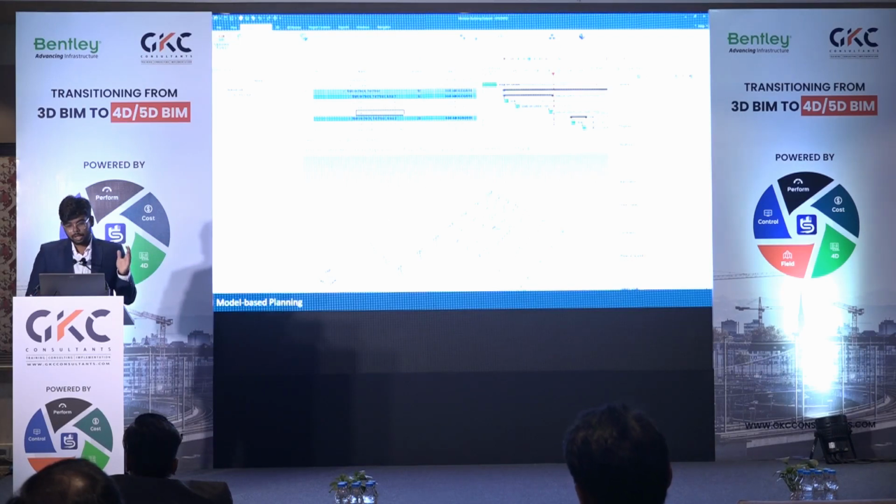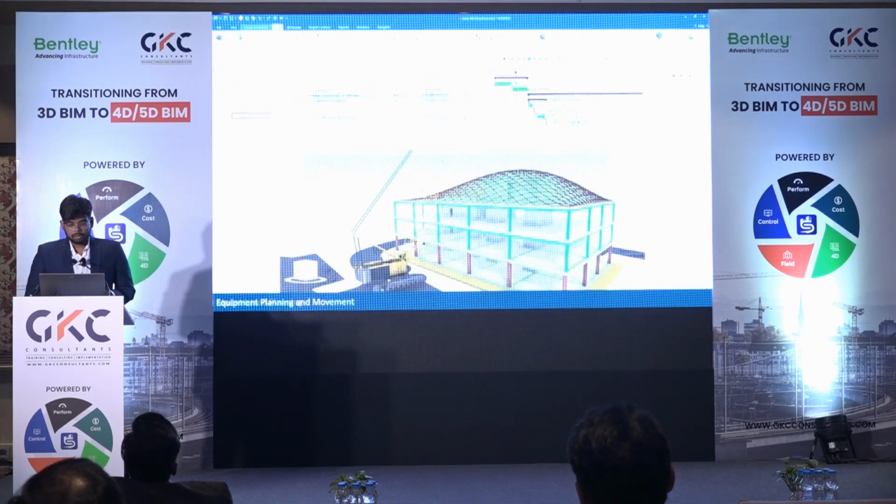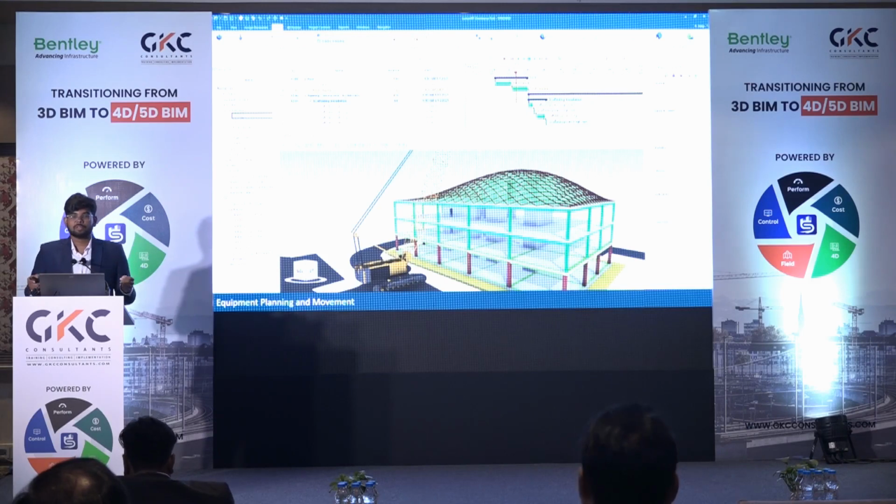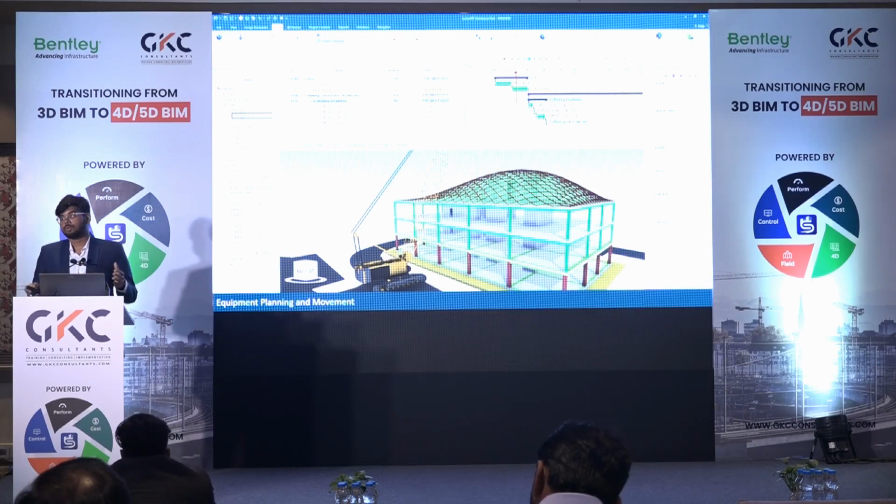So let's say that we have done a very good plan, and still one part we haven't considered is logistical planning. Another thing that Gantt charts are not able to communicate is where the equipment is going to stay and when the equipment is going to move in. We don't want only an animation of things going in, so that has to have some time information in it, and by that I mean accurate time information. That means the equipment is also treated as a 3D resource which will be assigned to the task.